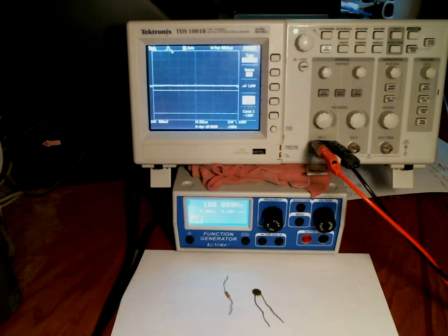So with the known capacitor combined with the known resistor, we can figure out what the RC time constant should be. I'd like you to go ahead and figure out that RC time constant, and also take 1 over that time and see what that would be in frequency units. So go ahead and pause the video for a second and do that calculation. Okay, so if you work that out, you should have gotten about 500 microseconds for the RC time constant, or about half a millisecond. And in frequency units, a period of half a millisecond would correspond to about 2 kilohertz. So that gives you some idea of the frequencies we're going to want to use.